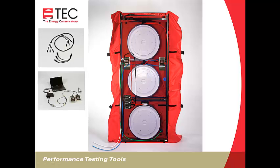Next, we've got a couple options on connecting to the computer. What we're showing here is on the top of each gauge, the gauges have a 9-pin serial connection on the top, and we'll screw these adapters on the top that go from serial to Cat5, and Cat5 is regular Ethernet cable that's pretty inexpensive and readily available. And then we'll use a splitter to combine the signal of 2 gauges onto one cable.